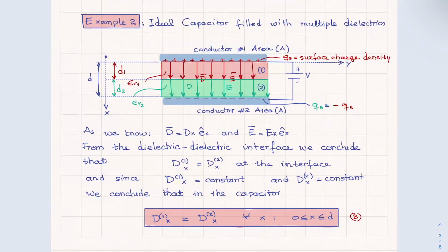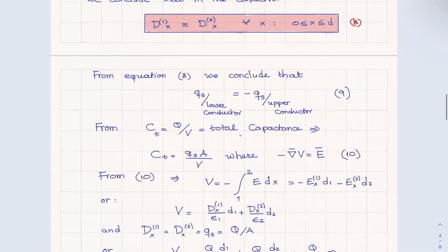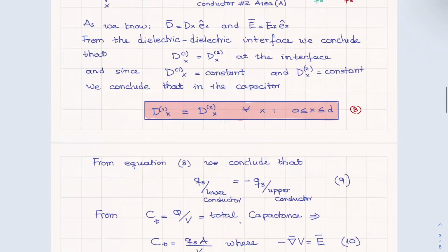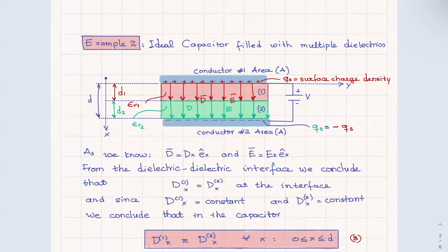We find that if we were to consider each dielectric on its own with a capacitor as being a separate capacitor, as if, for example, we would place a metal somewhere here, all right? But a floating metal. Let's assume that we place a floating metal there. So each part of this capacitor, if that were to act as a separate capacitor, then practically what that tells you is you would have one capacitor here and one capacitor there, and you will have these two capacitors in series.